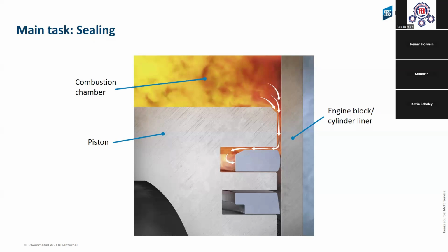And customers must also understand that when they use an engine for a long period at idle speed without a load behind the piston rings, they can have problems in the future with this engine, oil consumption, or also other parts that I will show you later.